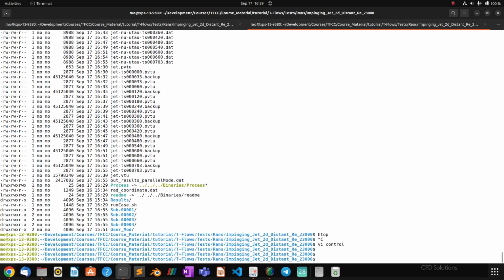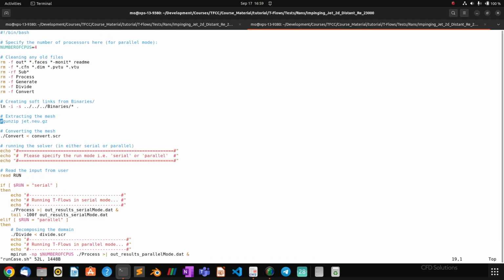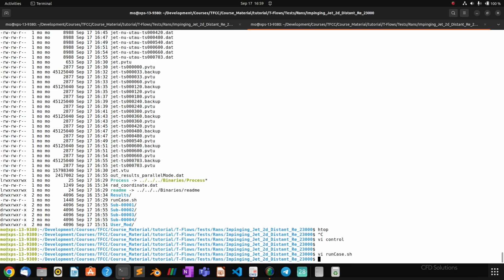In order to restart the solution now, maybe you need to modify the bash script, which is this one, but maybe an easier option is just to run it manually yourself by mpirun. So this is mpirun -np and the 4 processors that we're using, and put the program name, which is the program name that we need for this, and then you flush it, and instead of this file that we have already, maybe you say output 2 or the log file 2, and don't forget the and sign in the end.